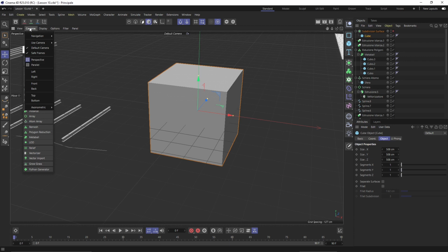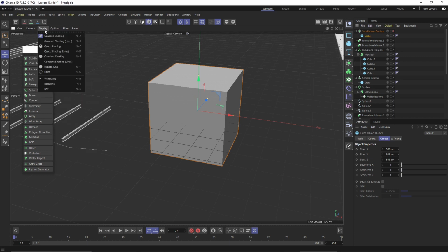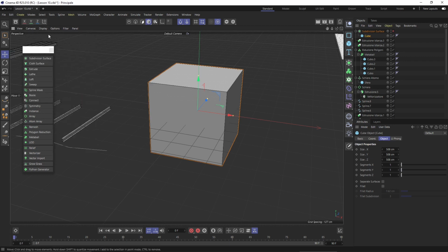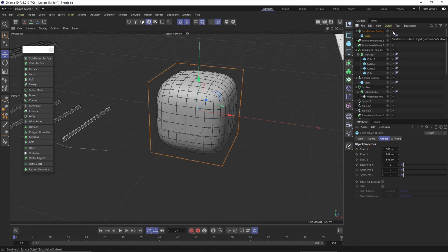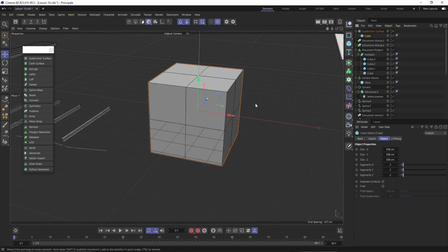Now, if I increase the number of segments or subdivisions in this different view, and smooth again, you can see the smoothing is now less aggressive than before because the object is protected by the segments, essentially.